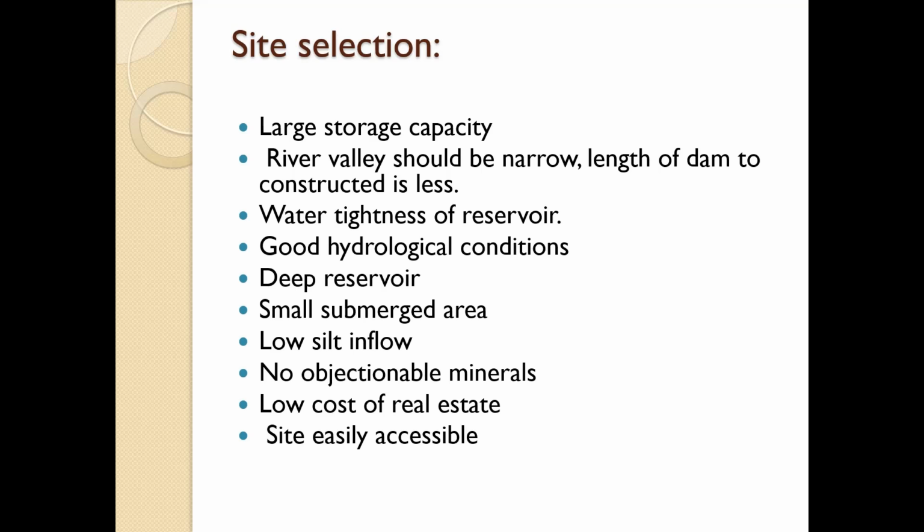What are the criteria for the site selection of a reservoir? So obviously large storage capacity should be available. Then the valley should be narrow, and the length of the dam to be constructed should be less. So obviously less area will come under the dam construction, so that it will be economical. Then water tightness of the reservoir is necessary. Then good hydrological conditions should be there. Then the reservoir should be deep.